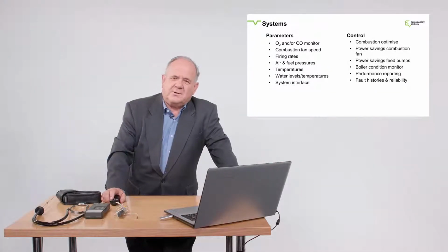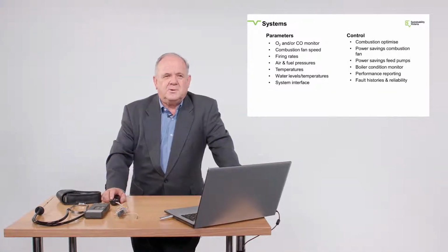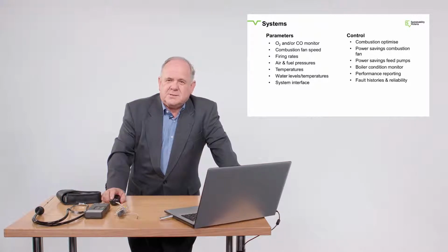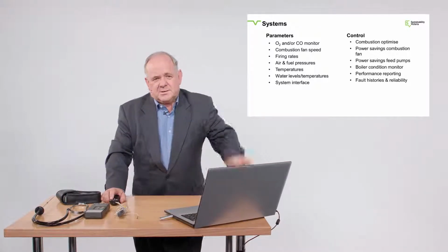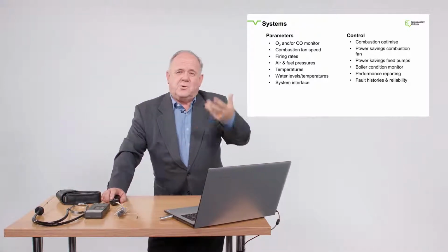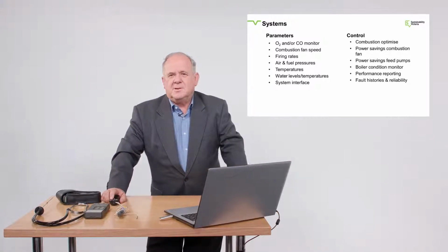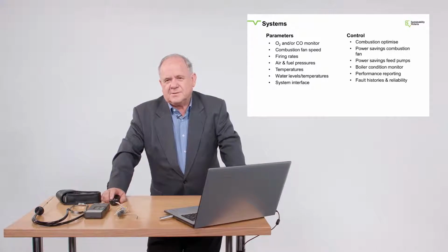So if that boiler fails, it's good for him to know what's wrong with it before he arrives, so he's got the right parts and things. With the new controllers, you can tell that. You can do a self-diagnostic with the control systems and you know exactly why the boiler's failed, so you can tell him and give him a heads up before he arrives to fix it. It's important because every hour lost production can be significant.